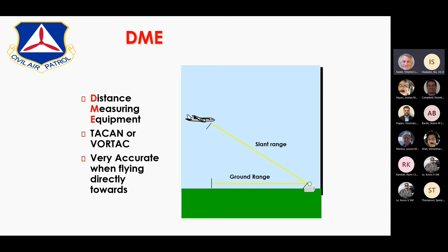DME in G1000 airplanes is not really radio received. In the G1000 airplanes, remember that it is simply synthesized from the GPS position and calculated. So when we talk about DME, one of the quiz questions may be this business about slant range. This picture shows you that the airplane is, let's say, a mile high, so it's at 5,000 feet.